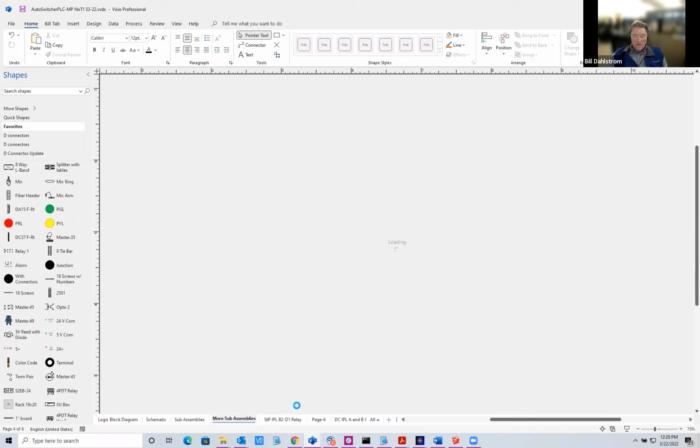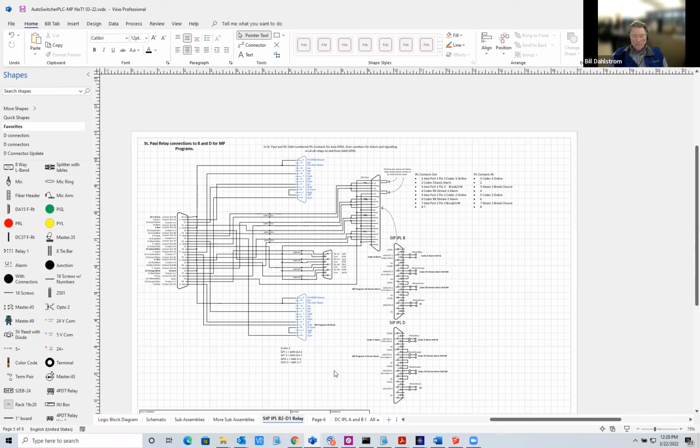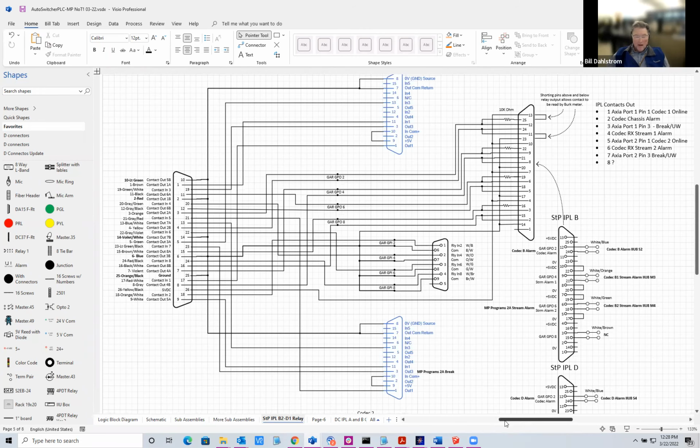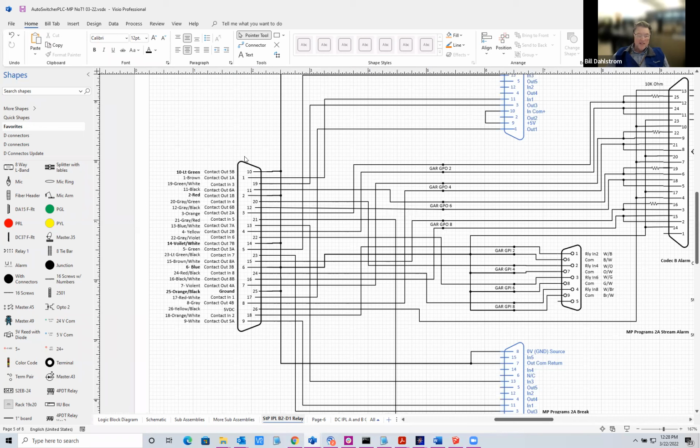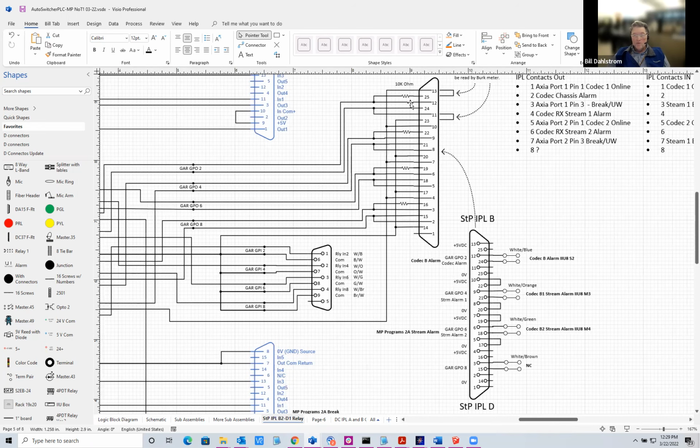Now we're loading. There we go. This is another drawing. This is just of a cable. There are a couple of resistors in here so I can do some pull-ups for meter readings. But this takes this 26-pin cable and breaks it down. I used to solder on these 26-pin connectors. This is a 15 size shell with an extra row in the middle. And I just decided I didn't want to do that anymore as much as possible. So what I did is I went out and bought a cable that's got the end on it. So it's got this end, and I put the color scheme in it, and then I can cut the cable and just take the individual colored wires and move those out onto the pins here.